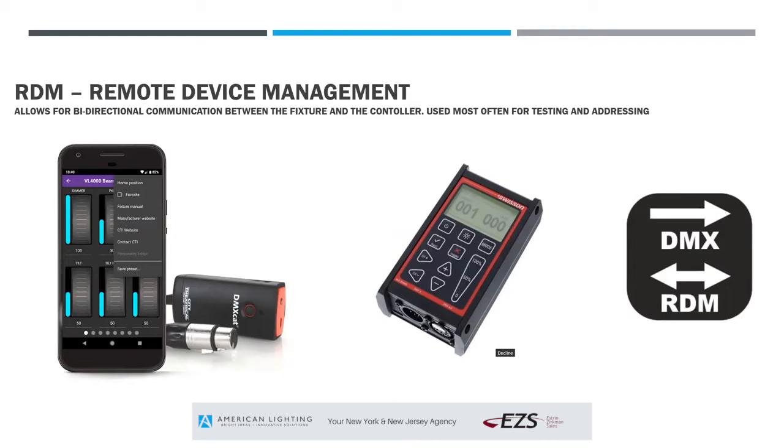Call the electrician, call the maintenance people and say, hey, fixture number 7 seems to be offline. Can you go check it out? It may be dead, it may be defective, it may have been bombarded with hail. Maybe the window washer came by and disconnected a cable by accident, and you simply plug it back in. But RDM is allowing for a lot of two-way communication and data management within DMX systems, which is really nice for end users and owners to have.